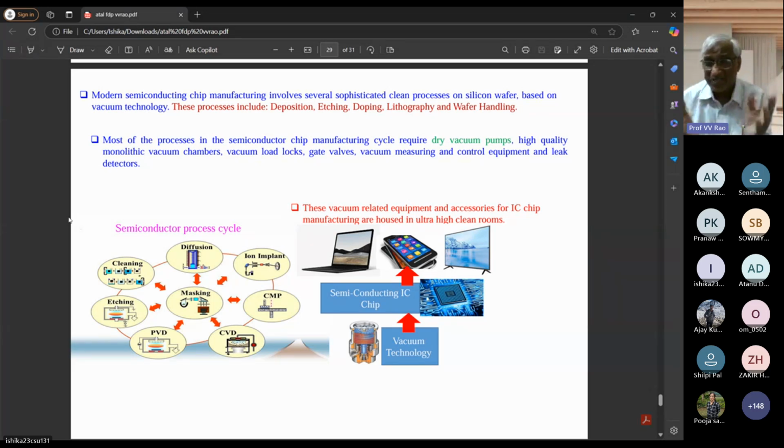When you take a capacitor, these capacitors are not like small capacitors like these boxes. These are not the capacitor. This is micron level, because capacitance is epsilon naught A by D. So if you can reduce the gap D, you can increase the capacitance. Or else you can increase the epsilon. That's why special dielectrics are now being prized. Originally, 10 years back, you only had 10,000 to 20,000 components per square inch, so you could afford a little bigger capacitor. In normal practice, normal oxidation is enough. The oxide layer itself, silicon dioxide, acts as the dielectric.